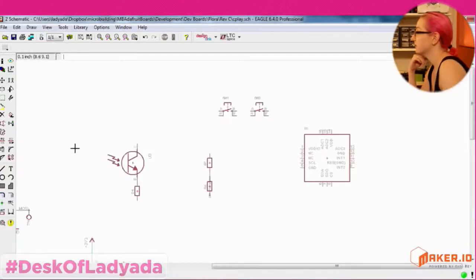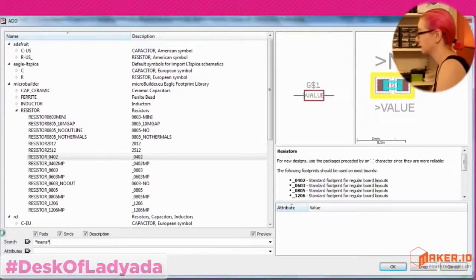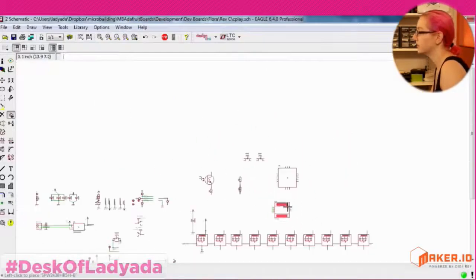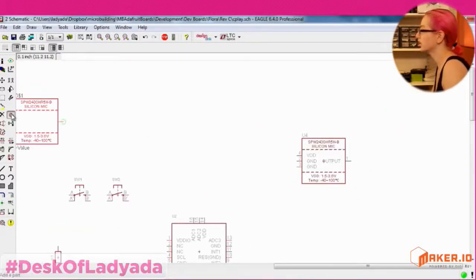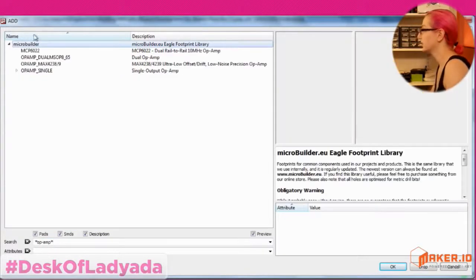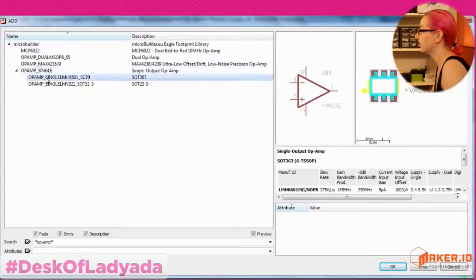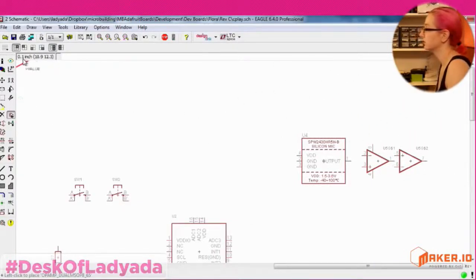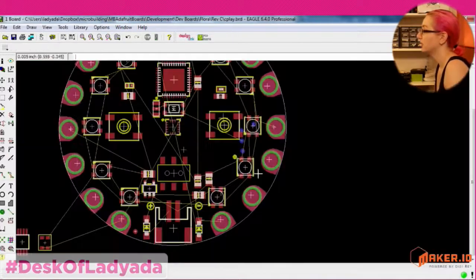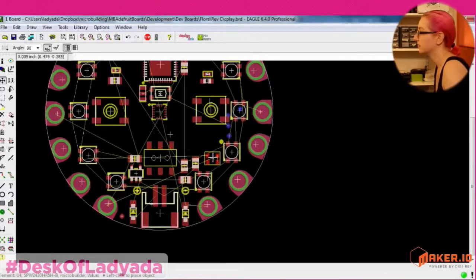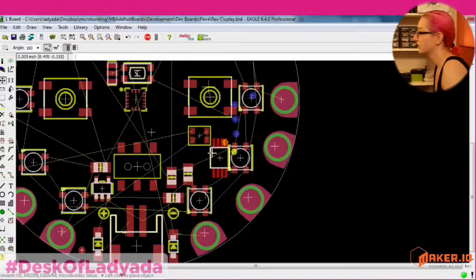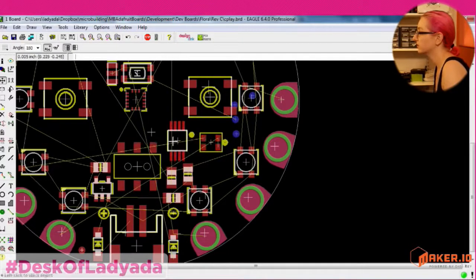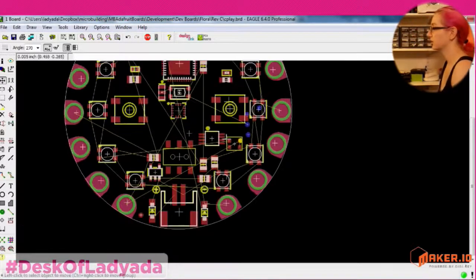And then I have the MEMS microphone. So let's see. No, it's called the SPW, yeah, silicon microphone. And the output of this microphone, unfortunately, does require an op-amp. So I picked, not exactly this one, but basically I picked a dual op-amp to amplify and buffer. And there's going to be, of course, some passives that go with that, but we'll pretend like we'll do those later. So this is the microphone circuit. Just kind of figure out where you want it approximately.